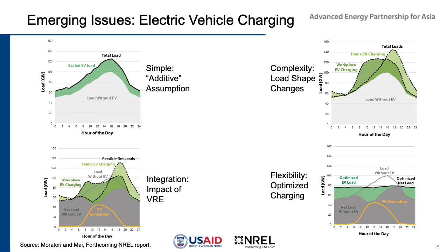And then things can be increasingly complicated in a scenario such as that. And then finally, in an optimized way, we could see how flexible load and PV generation could result in a more optimized EV load, which is much more of a straight line. And not always, but typically, the more you can flatten out the demand or the load profile, the cheaper it will be to operate your system.